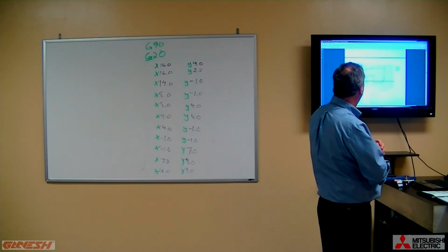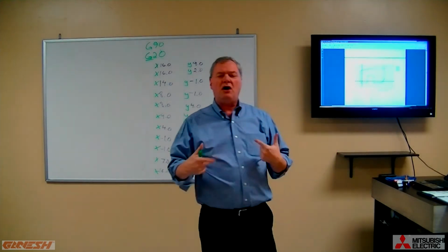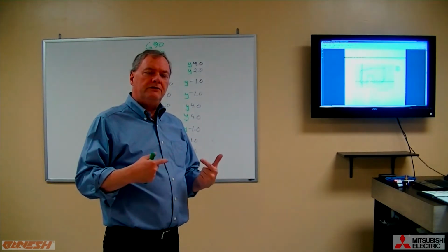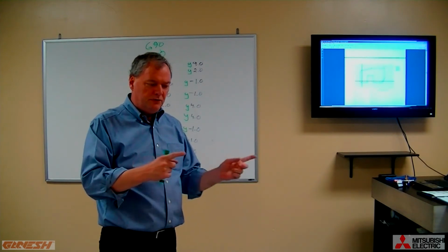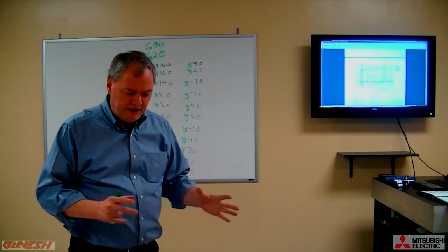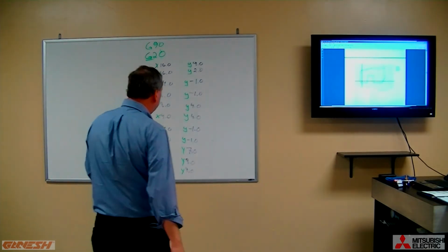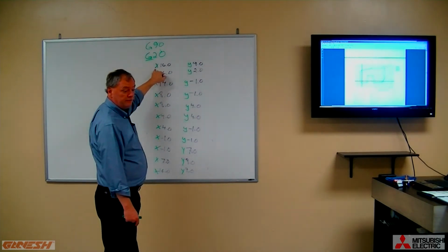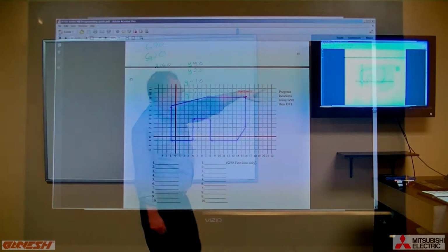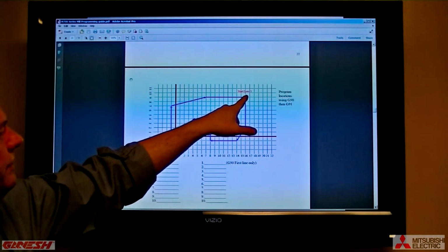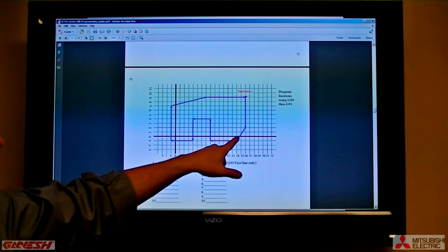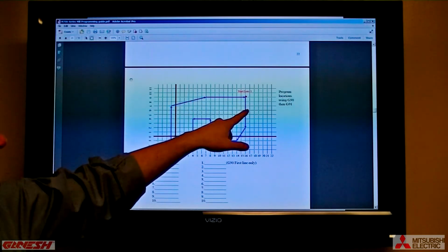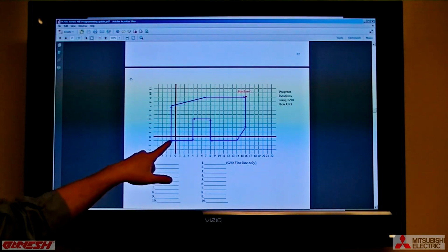What we are doing is now introducing you to other functions within the CNC control. So remember, CNC controls are axis movement, in which case if you wanted to make axis movement, you simply tell it where you want to go in terms of a coordinate and which axis you want to move. So here you see we're making a bunch of X and Y moves. What the controller is literally going to do is follow the order that you've keyed in these commands, point 1, point 2, exactly as you've typed them in.